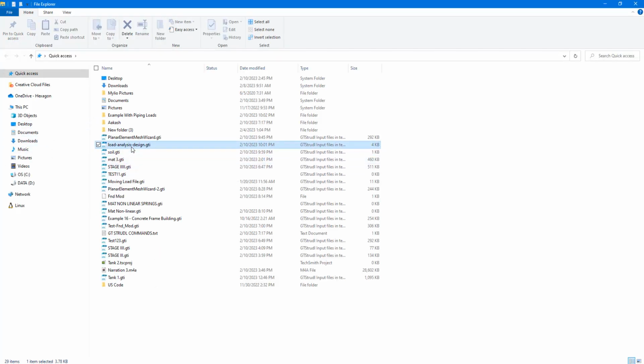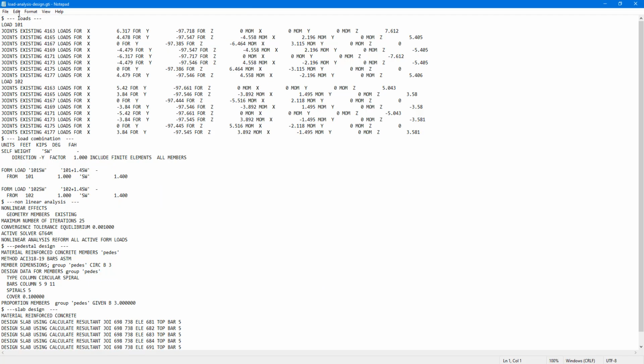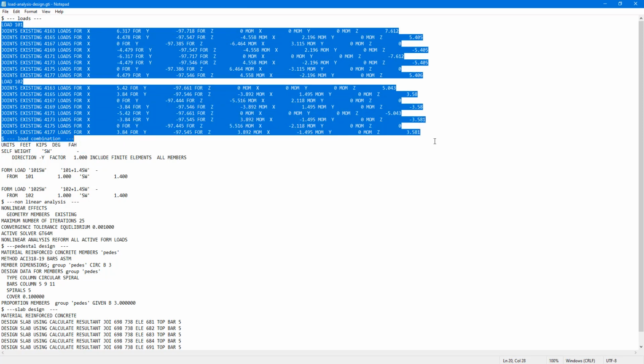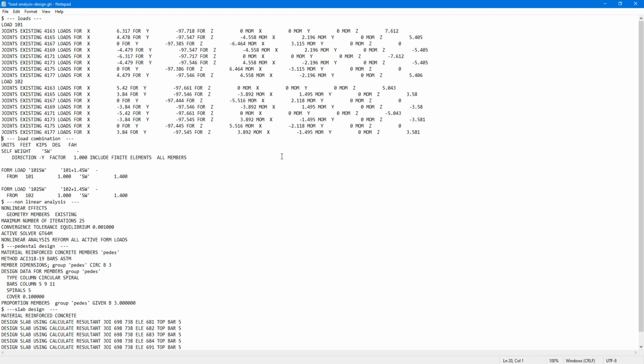Here, this is the file that I have, and you can open it using any Word or Notepad file, and you can just select all the loads and just copy and paste, Control V. Okay, so anything changes on the structural side, all you need to do is just copy and paste those. These node numbers are basically coming in from the steel structure. So you can easily reference where these loadings are coming from.